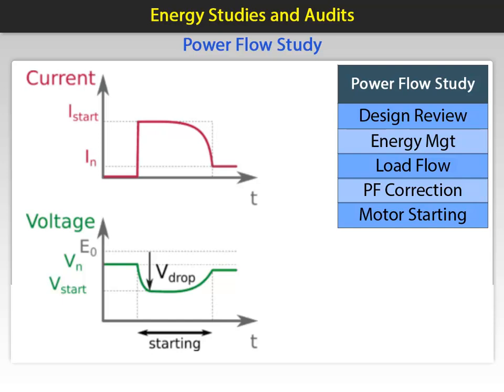Measure inrush current profiles using high-speed power monitors. Simulate motor starting scenarios in power system analysis software. Analyze voltage dip and recovery time at different buses. Examine utility bills to develop a history of high demand times.